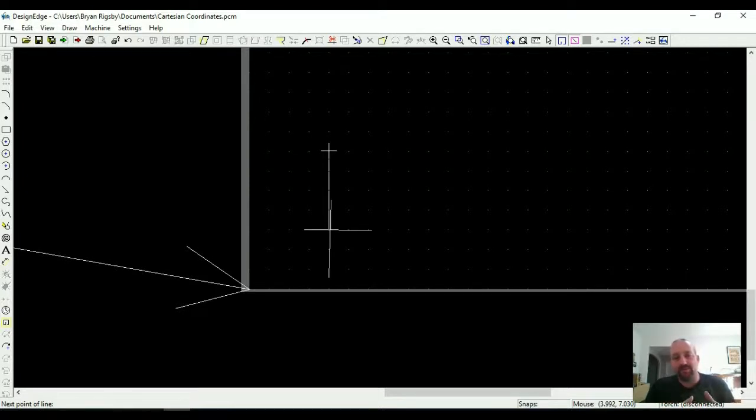So the process we're doing is drawing a line. We've entered our first point with an absolute coordinate, so we know where we're starting. And now we want to make the next point be 3 inches above that first point. So we'll put an @ sign, which is shifting the number 2. And from this point, let's pretend like this origin down here is moved to this first point of our line.